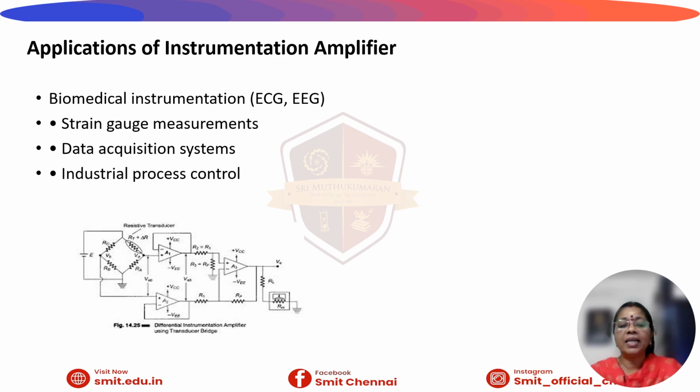Most sensors like strain gauges, RTDs, and pressure sensors are resistive. To measure the small change in the resistance, they are placed in the bridge circuit. The DC supply voltage always powers the bridge. When the physical quantity is at its base state, the bridge is balanced, that is V1 is equal to V2, and the differential output is 0 volt.